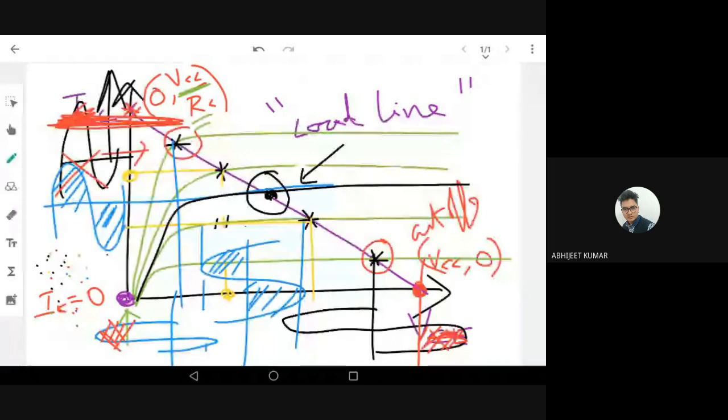So if your amplifier working in Antarctica is not working exactly like in Delhi, and the same one working in Delhi is not exactly working in New York, this is not good. It is a very different circuit having different parameters, and this is a problem. So as an analog circuit designer, you have to fix the Q point. Your circuit should be independent of all those external parameters. This is the challenge of the designer. You have to fix the Q point or the operating point of the transistor so that you have good, proper amplification.